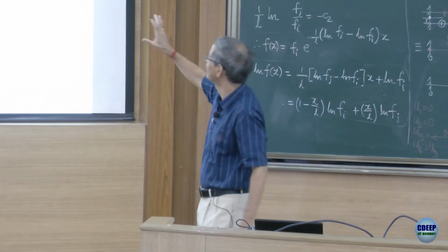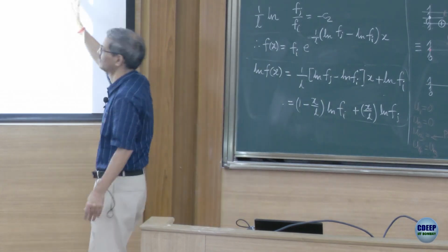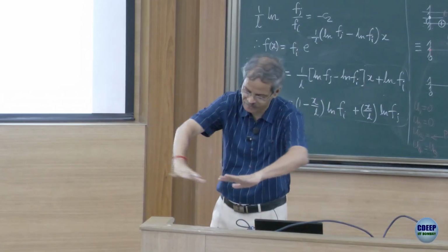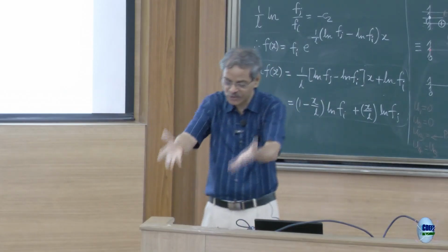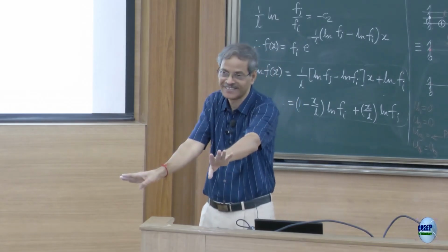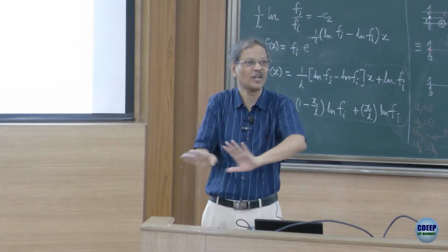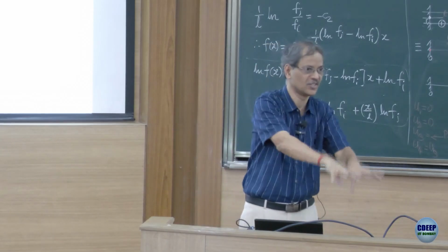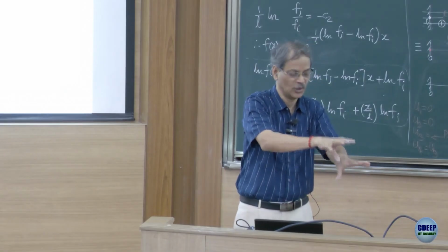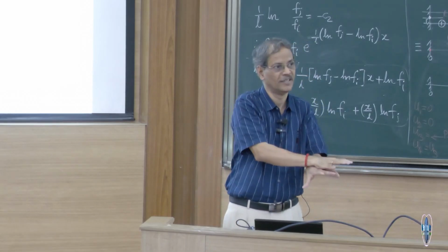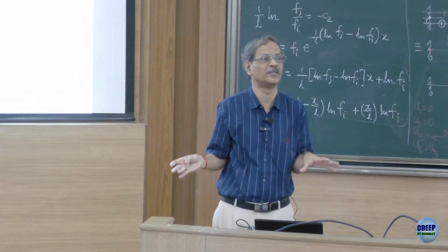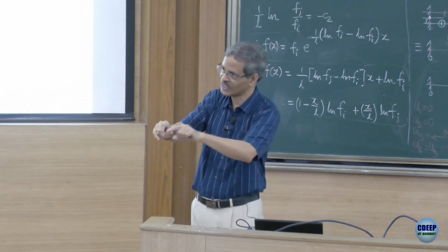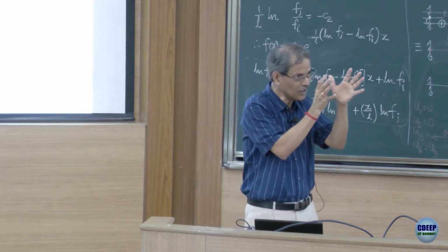All that I am interested in is in this real physical world, I agree. Field variables variation over the real physical world, its derivatives with respect to x and y, first derivative, second derivative, whatever is of interest to me is with respect to x and y, I agree. But computations I want to do in this zeta eta frame. So, this would mean a coordinate transformation. When I do a coordinate transformation, I am saying that for every point in the real physical world, there is a corresponding point in this 2 by 2 square.